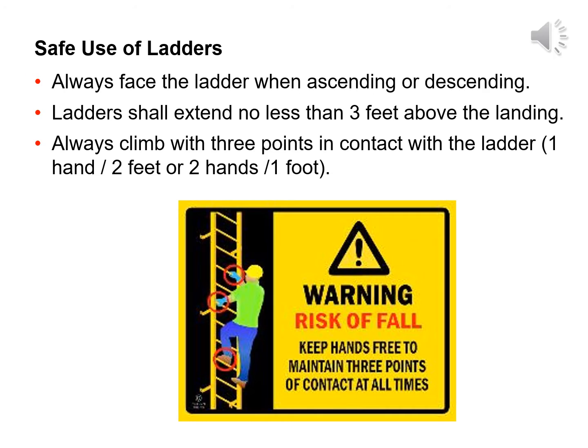When climbing a ladder, it is safest to utilize 3 points of contact because it minimizes the chances of slipping and falling from the ladder. At all times during ascent or descent, the climber must face the ladder and have 2 hands and 1 foot, or 2 feet and 1 hand in contact with the ladder cleats and/or side rails. In this way, the climber is not likely to become unstable in the event one limb slips during the climb.